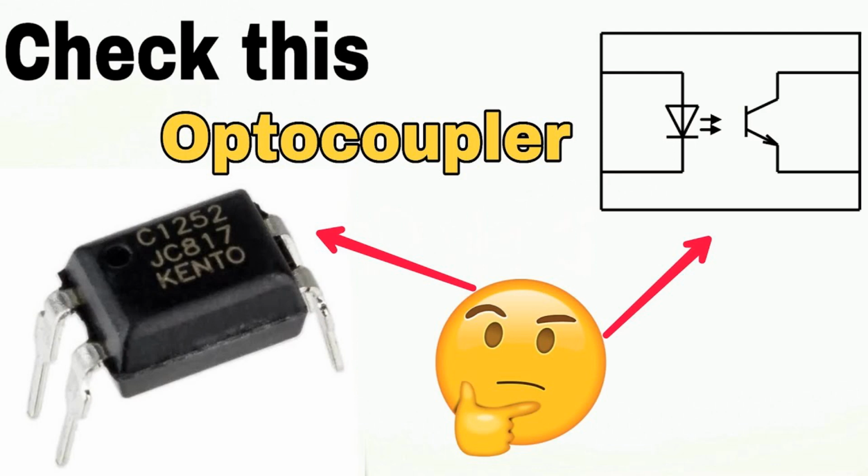Isolation. Signal isolation can be part of signal conditioning, especially in situations where electrical safety is a concern or to eliminate ground loops. Isolation techniques, such as optocouplers or magnetic isolators, are employed to separate input and output circuits while allowing signal transmission. Digital conversion. Analog to digital converters, ADCs, are used to convert analog signals into digital form for processing by digital systems. Signal conditioning may include ADCs to digitize analog data accurately.